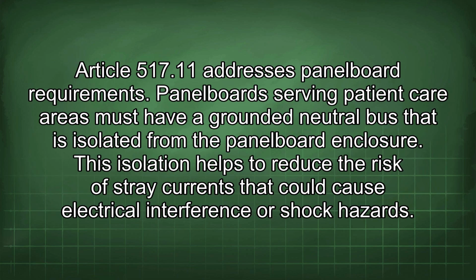Article 517.11 addresses panel board requirements. Panel boards serving patient care areas must have a grounded neutral bus that is isolated from the panel board enclosure. This isolation helps to reduce the risk of stray currents that could cause electrical interference or shock hazards.